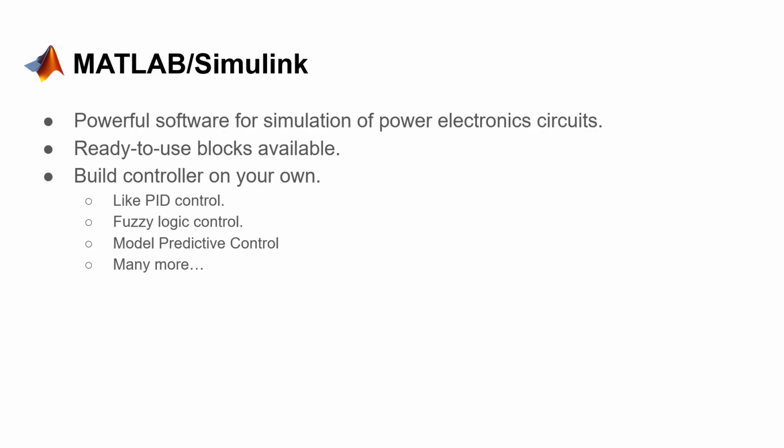For instance, you want to build a model which will convert the voltage from AC to DC, and you want to control the DC voltage. Assume that the converter we are using has thyristors. To control the DC voltage of a thyristor controlled rectifier, it is important to select the right firing angle.